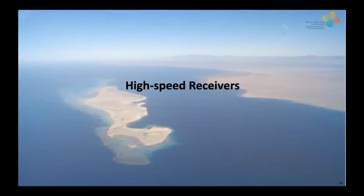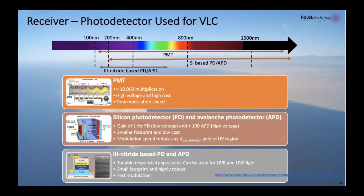today. Let's switch gear and talk about the receiver. For the photodetector for VLC, we can have several options. PMT is somewhat bulky, but it covers a very large range of wavelengths, from about 200 nanometers in the UV all the way to near IR at 1500 nanometers or so. Another one is the relatively low cost silicon photodetector and the APD on silicon, also covering from 200 something nanometers, going all the way to not that long a wavelength of near infrared, but the far red also.